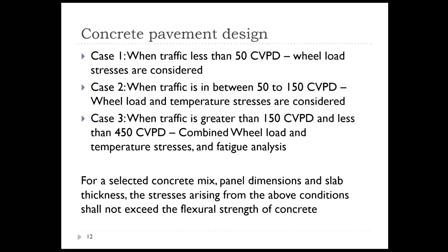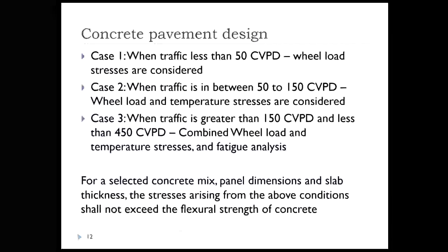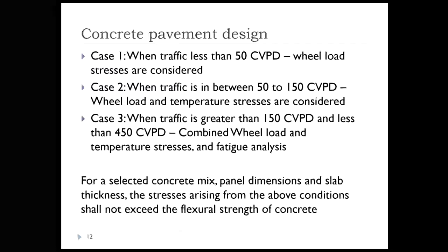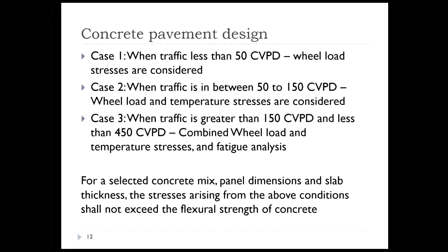Now the essence of any concrete pavement design is that you calculate the flexural stresses arising because of wheel load stresses and temperature stresses, the combined stress or the critical stress combination. The critical flexural stresses, whatever you compute, should not exceed the flexural strength of concrete, whatever you are considering. This is the essence of your concrete pavement design.